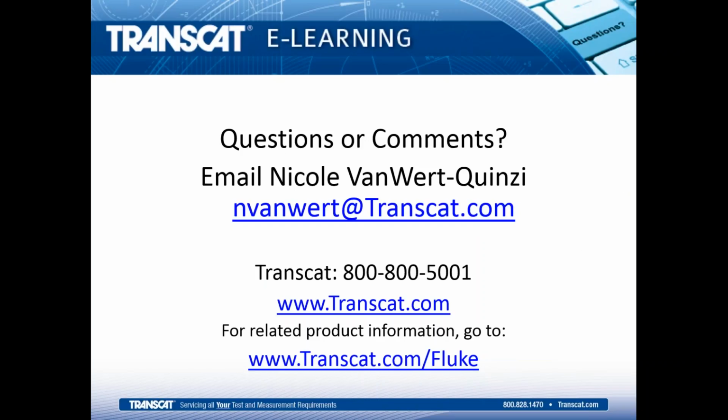All right, so the first question, how often do I need to calibrate RTDs? Okay, that's a great question. Calibrating an RTD is going to depend on the manufacturer specification, and sometimes they'll have one specification for a higher accuracy up to 6 months, and then the accuracy is pretty good over a 12-month period.